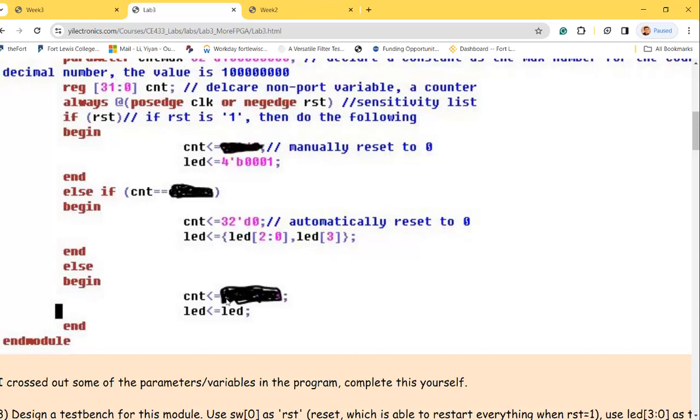So it's running, like I said, on the rising edge of the clock. Whenever the clock has a rising edge, it's going to update everything in there. For most of the cases, it's reaching the else instead of somewhere on the top. It takes such a long time to reach that count max. So this one is being updated 100 million times a second. It's counting really quickly.